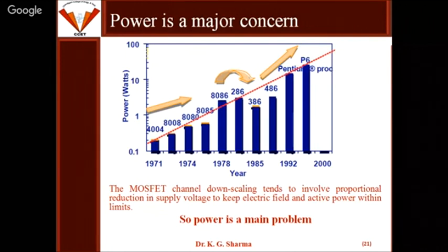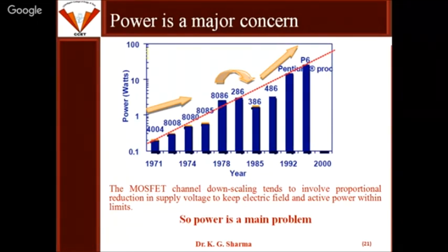So we should also have some concern about how we can dissipate this power so that the device is not affected by it. In general, if you have seen a computer, there is the SMPS and there is some fan at the top of the microprocessor as well as some other places. That is only there to dissipate the heat. If heat is not dissipated properly and the heating components are not properly distributed over the chip, then surely the chip is going to be burned.